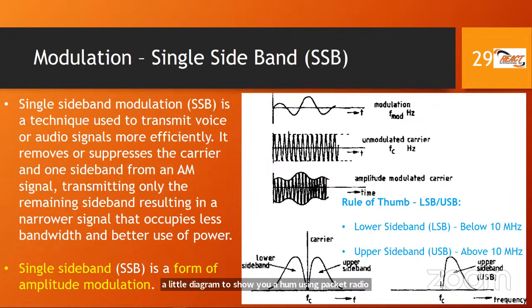All right, so we need to be very familiar, and hams are quite familiar with this mode of transmission or this modulation scheme called single sideband or SSB. So let us go into a little bit about what SSB is. What is single sideband? So remember we said we have our carrier wave and we'll modulate it and we'll have a transmission and so on, right?